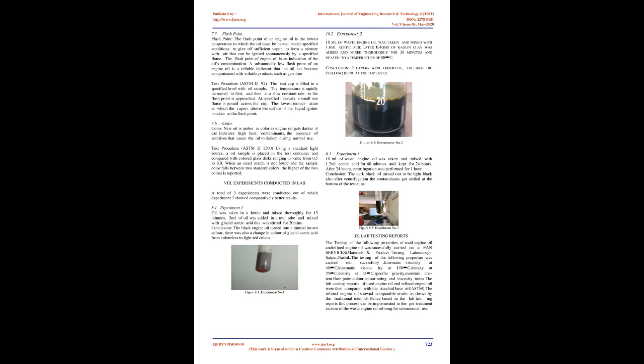Test procedure: ASTM D5349, the oil sample is weighed and air dried to equilibrate it with the atmosphere. The residual moisture is then determined using the drying oven method. Air drying and residual moisture are combined to report gross moisture. 7.4 Density.